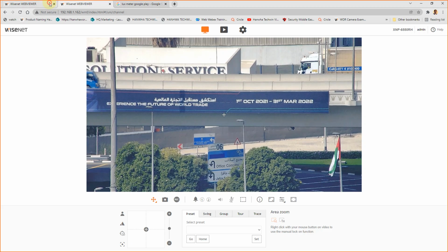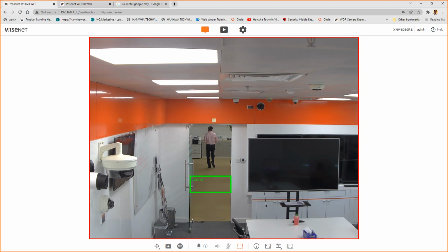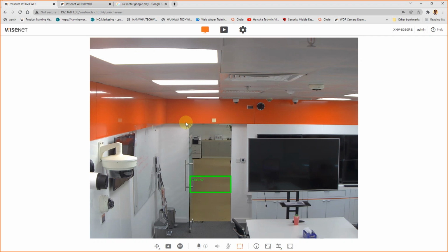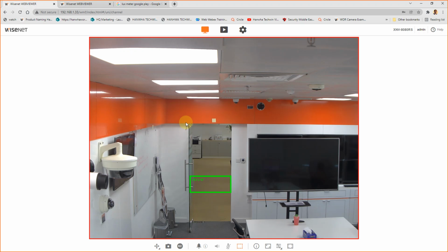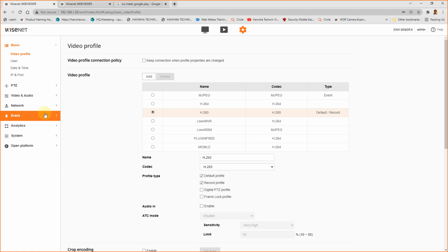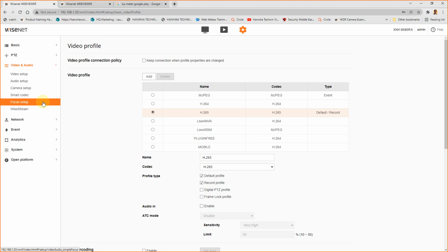So in hotel entrances, the chances are the lighting is very dim. Okay. So how do you still guarantee identification? Because identification is a must. We cannot sacrifice it: you don't know which country the guest is coming from, and you need clear details of who is in your property. So there, if you have low light locations and you need identification, just jump the requirement to 500 pixels, double the minimum requirement. So for sure, you're not going to miss anybody walking through the door. That's as good as 120%, you can compare to that level.